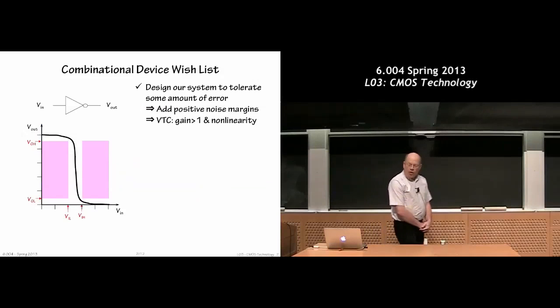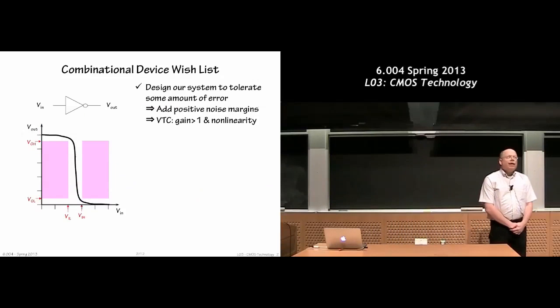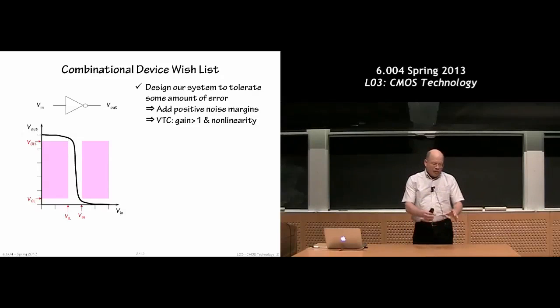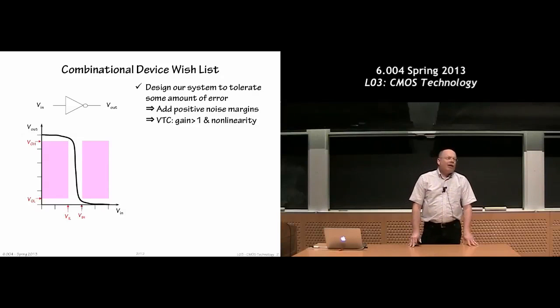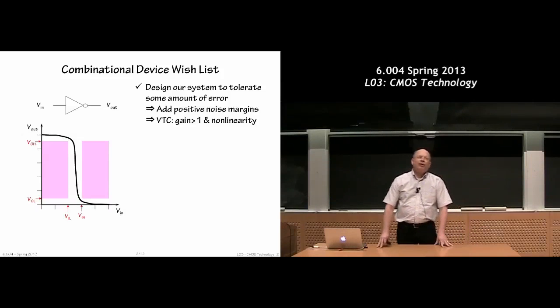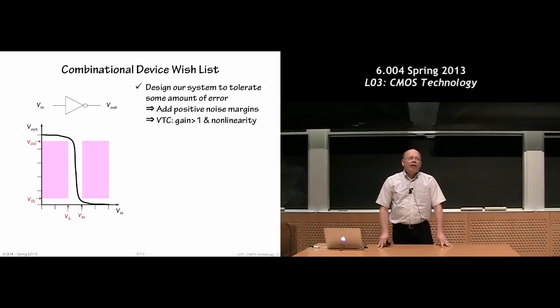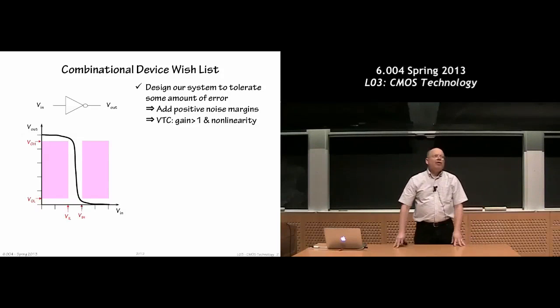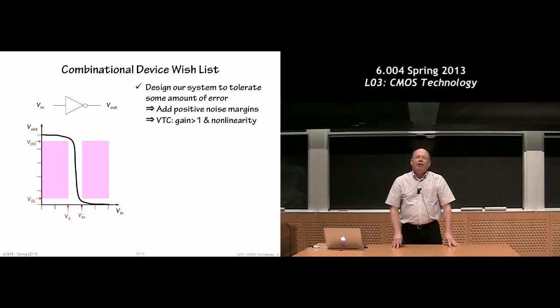So last time what we talked about was a couple things. We set out a set of construction rules that we called the static discipline for how to assemble, given combinational device building blocks. The static discipline are rules that constrain what a combinational device has to do. And then we figured out how to hook those up in big acyclic networks, being careful not to short any outputs together. And when we did so, we discovered that we could actually build very, very large systems. You could put together some of the building blocks to make your own new, larger building block, and then I could borrow your building block and use that to build my system.